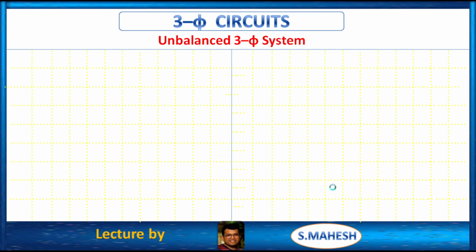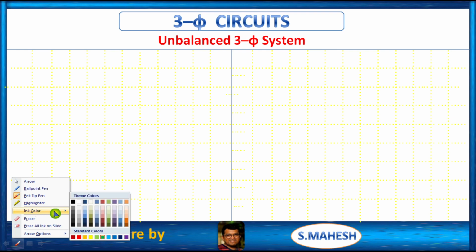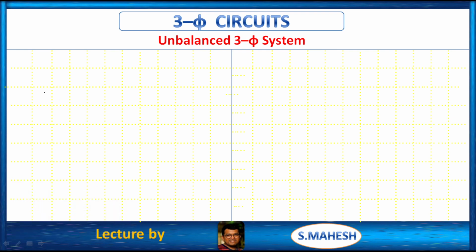Okay, next, due to flow of these unequal currents in each of the phases, a voltage appears at the neutral and its value can be VON. In case of a balanced system, we don't have any neutral current, obviously we don't have any neutral voltage, but due to these unequal currents, obviously we are having a neutral voltage. Before that, first we have to draw the connection diagram, how we can get the neutral current and how we can get that fourth wire in case of star connection.